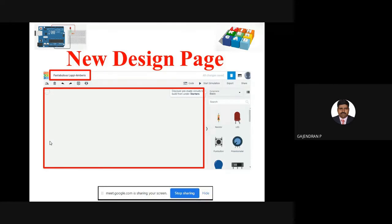Then this is our main window. This is our working space where we are going to keep our original hardware components. From here we can fetch the components. Just to the right side, you have a component window. From that window, you can select the components. For example, in this monitor you are seeing resistor, LED, push button and potentiometer. We need to click any one component and drag and drop it in the workspace.